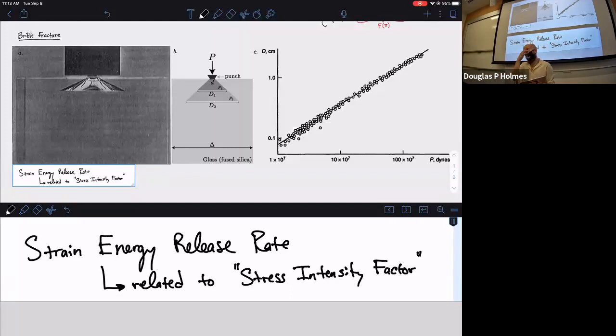I like to think about the stress intensity factor as a way to quantify stuff that we know intuitively. For instance, take a rubber band, put a notch in that rubber band, just like a tiny little defect in it, and then stretch that rubber band. You know that that rubber band is going to break right where that defect is. That little defect is going to propagate through the material and cause this thing to fracture. And physically what's happening is that you're applying some amount of stress to this material by pulling on it, but that stress is going to be amplified near this crack.